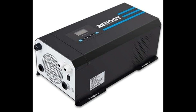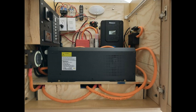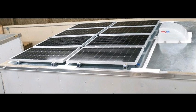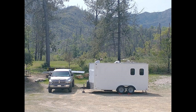The trailer's power system uses a 3000 watt pure sine wave inverter with a built-in 75 amp charger. There is a 30 amp shore power connection and a manual transfer switch. There are two solar charge controllers. One 60 amp controller is connected to the 8 100 watt solar panels on the roof of the trailer, and there's also a 100 amp solar charge controller for use with the 1600 watts of solar panels mounted on the bed of the pickup truck. This gives a combined solar charging system of 2400 watts.